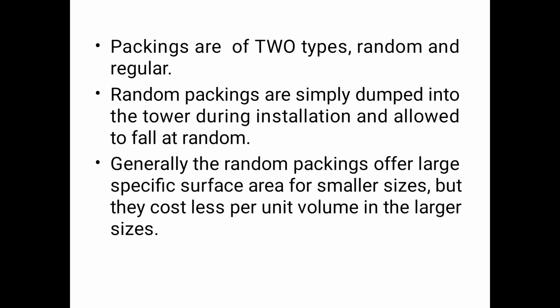Generally, random packing offers a large specific surface area for smaller sizes. If you use smaller size packing materials, it has a larger surface area, but the cost per unit volume is less in the larger sizes.